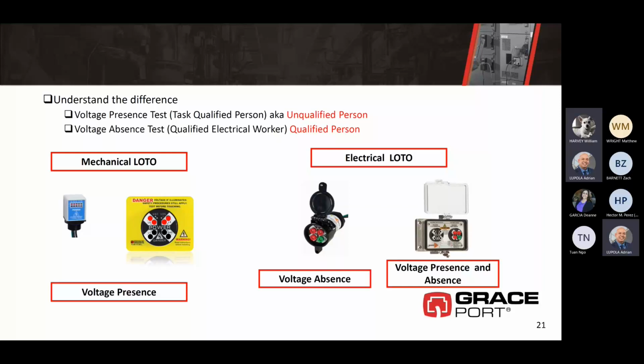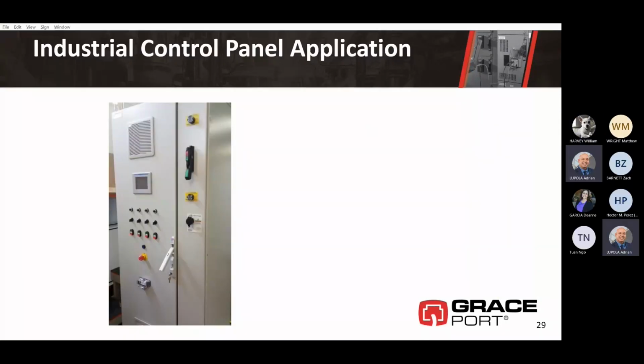All right, next slide. And this is just an application showing some on the door. You see up at the top there a voltage indicator. That tells me I have line voltage coming in, right? They also put one down below. If that's a fusible disconnect, that also acts as a blown fuse indicator. So if the switch is on, both of those should be lit up.